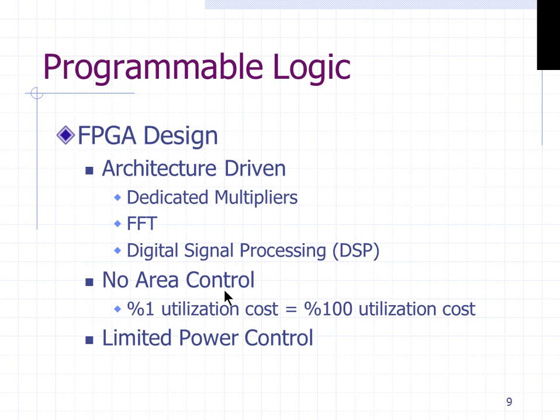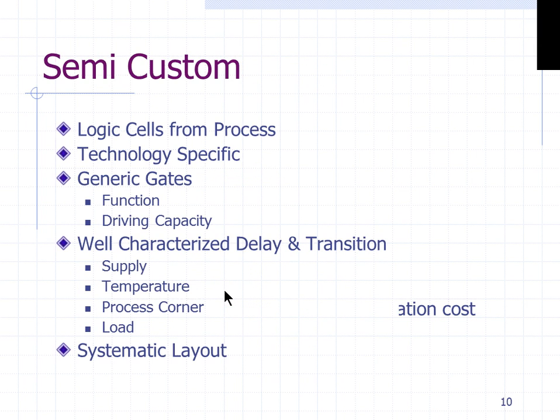So those things are nowadays supported by FPGA design tools, where you can also do analysis of your design. After placement and routing of your FPGA, you can run a power analysis on the design. It will generate a power report for you, and you can analyze the report for where the power consumption is. In ASICs, all this power control was always there because it was required to do a power analysis and any corrections required before we went further. But with FPGAs now this is available as a part of the tool set. So this was FPGA related.